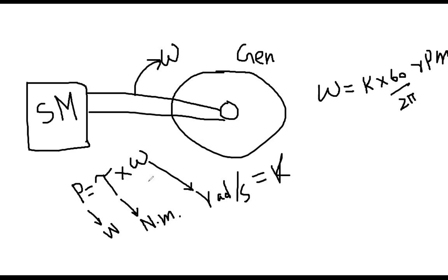So Sindhuja, can you follow me? Yes, Dr. Ali. First, please write down this equation: power equals torque multiplied by omega. This is speed, but it is in radian per second, not in RPM. And this is for the synchronous motor, but the synchronous motor shaft is the same shaft for the generator as well.